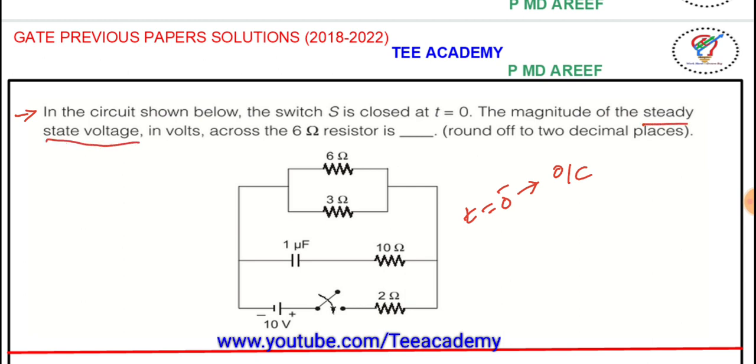Now see here, you have to understand the concept. At t equals 0 minus, is any current flowing here? No. Why? Because the source is not supplying current. The initial voltage across the capacitor, Vc of 0 minus, is 0. No voltage source is there, so there will be no current. No current means no voltage drop, so there is nothing to discuss about the t equal to 0 minus case.